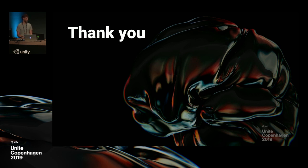You're welcome. We have 2 minutes left. One more quick question. For example, typically on the car, the 4 tires are the same. Do you have an algorithm to detect that so that the mesh is the same for the 4 tires? Yes. Most of the time with CAD files, there are instances, like I said. So basically, you would have only one sub-assembly for one wheel, and it will be repeated 4 times. So when you do the job once, it will be automatically done for all the others because they share the same reference. And so the pivot would also be properly oriented. The pivot of the tire would also be mirrored. Yeah, properly. If you do a process on this sub-assembly of the left wheel, for example, it will be the same for all the others.